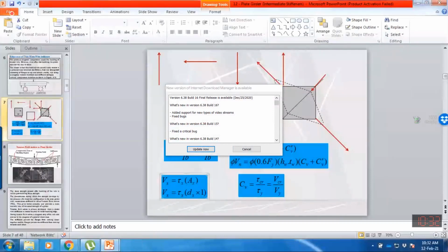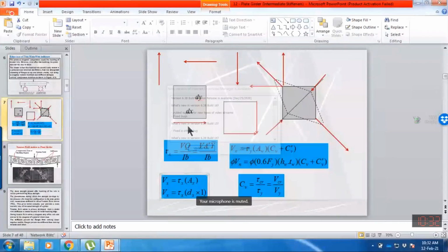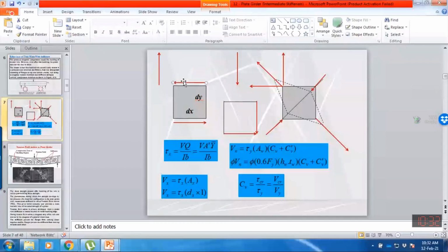So what do you think? Because on this element, we must have some reaction over here, some reaction here, and also reaction here to balance this free body diagram for the element, because these are continuous material, because we have cut. So what do you think? Is this element balanced? No. Just to balance this force which is acting in this direction, if we apply summation Fx is equal to 0, we must have a balancing force which must be acting on the top side.